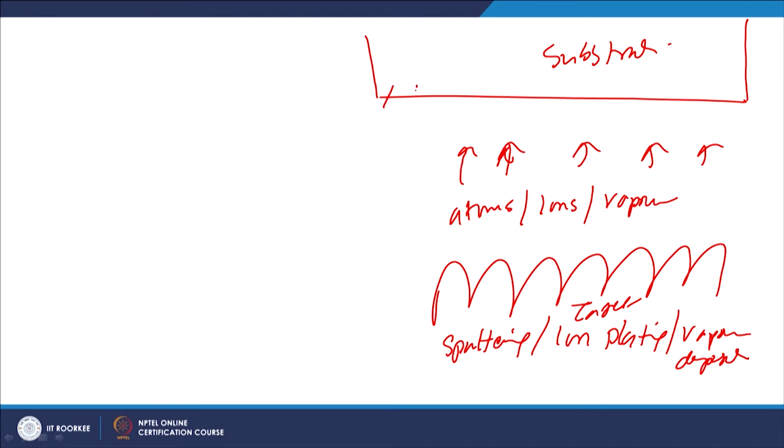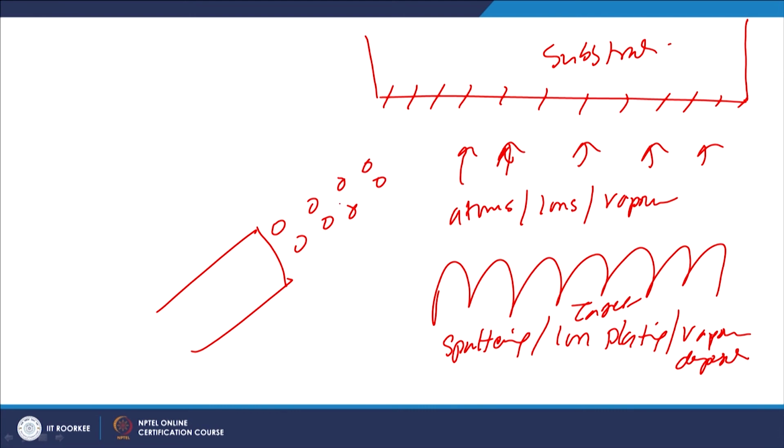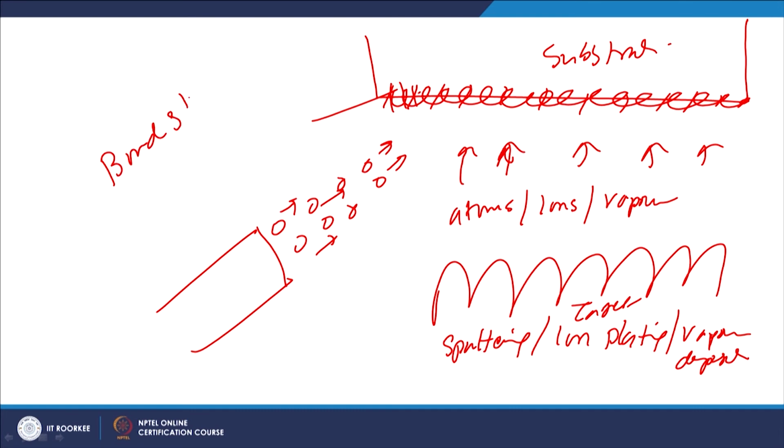On the substrate they will get deposited using a suitable independent source of the ion beam. This beam is directed onto the surface which is being modified. So, this ensures extremely good mixing of the material deposited, and this mixing improves the bond strength, results in a very good gradient, and reduces the metallurgical issues and other cracking tendencies associated with this process.